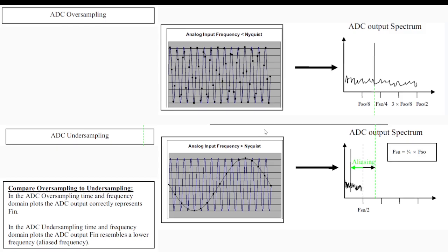And this is another very important concept relating to analog to digital conversion. One is called oversampling. The other is called undersampling. Undersampling means you are sampling a signal at a rate less than the maximum frequency in the signal. Oversampling is that you're sampling at a way higher sampling rate compared to just simply 2 f max. Maybe you're sampling at 3 f max or 4 f max, whatever.